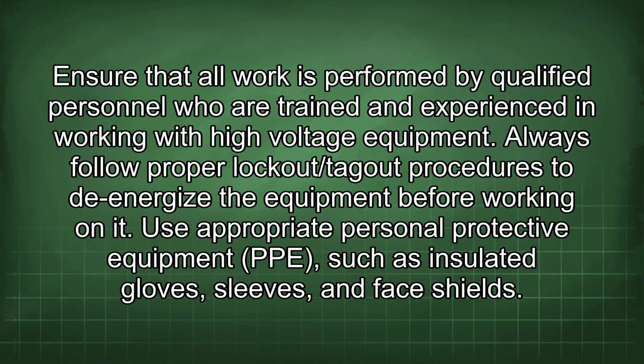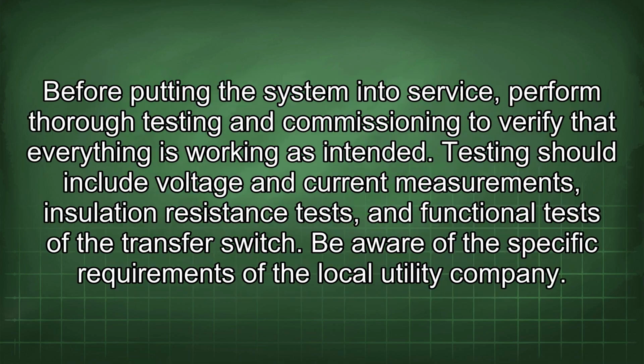Always follow proper lockout/tagout procedures to de-energize the equipment before working on it. Use appropriate personal protective equipment (PPE) such as insulated gloves, sleeves, and face shields. Before putting the system into service, perform thorough testing and commissioning to verify that everything is working as intended. Testing should include voltage and current measurements, insulation resistance tests, and functional tests of the transfer switch.